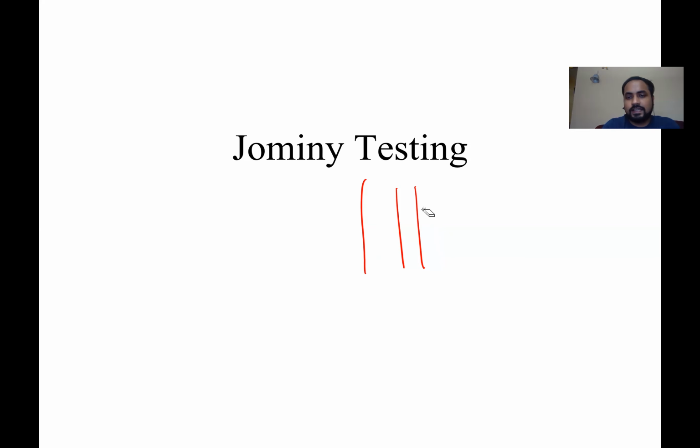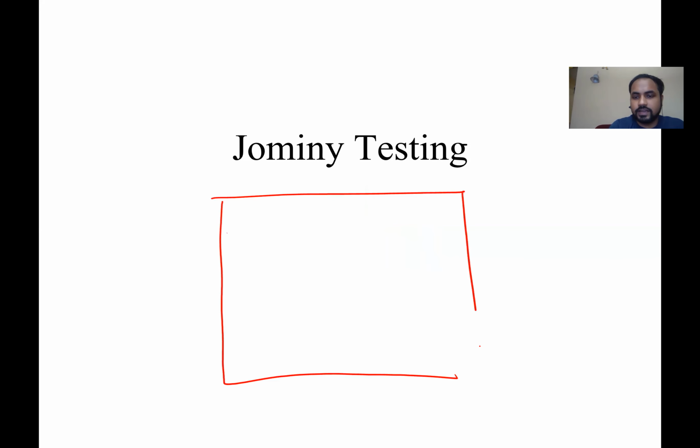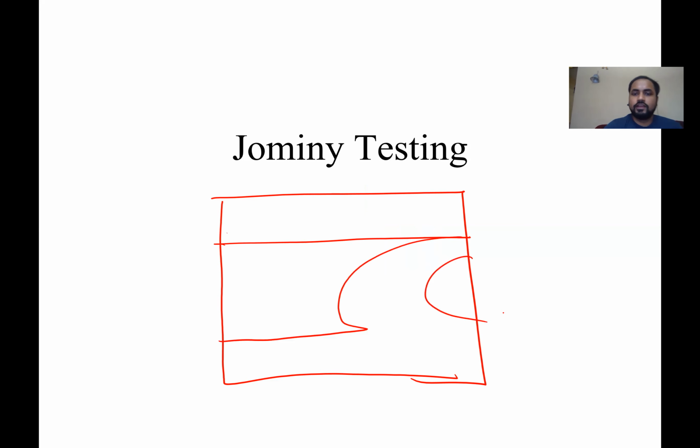And the biggest challenge why bainite is not talked about so much is, I showed you the TTT diagram, right? You form pearlite at the top, you form martensite at the bottom. This is a typical TTT structure. Let's say you want to form bainite, right?